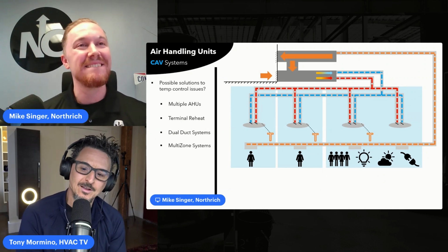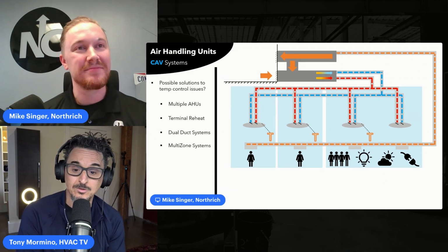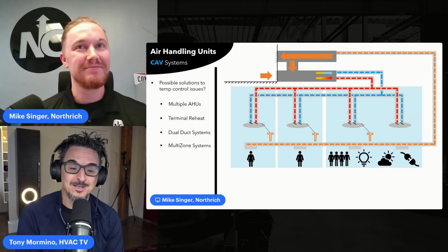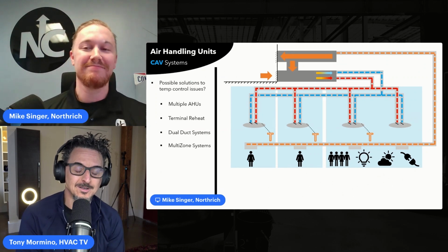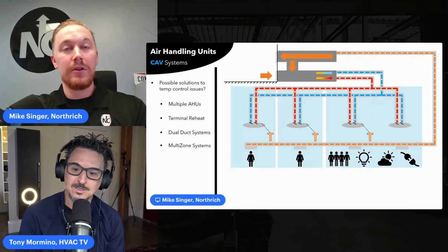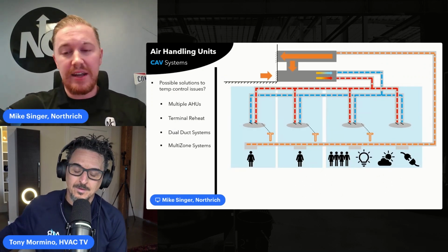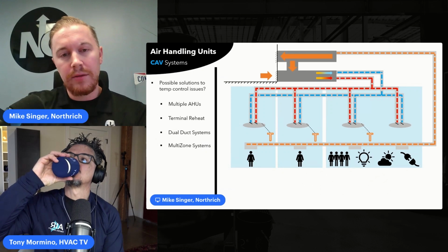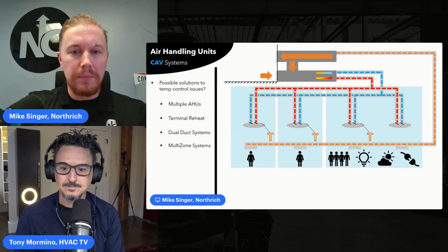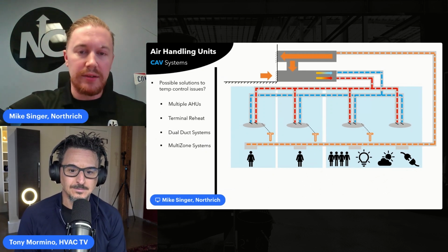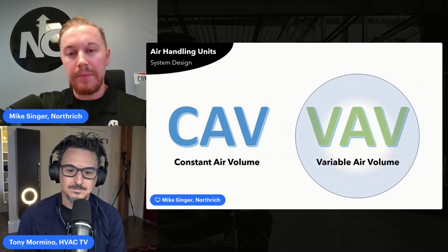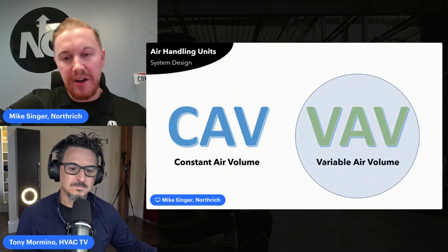I don't think I've seen a lot of those in the southeast. I've seen a lot of multi-zones. Mostly they're being replaced. They're great in terms of temperature and humidity control. I just don't think they're as efficient as newer systems. Do you see a lot of these types of systems where you're at? Older systems? We do. Yeah, we do. We just had a multi-zone job in Canton, Ohio that we were designing, and yeah, a lot of replacement work will replace multi-zones or dual duct air handlers. But the better solution is the VAV option. So, what is VAV, variable air volume?